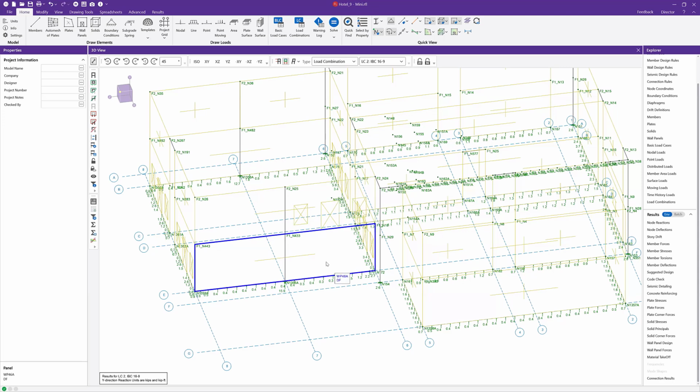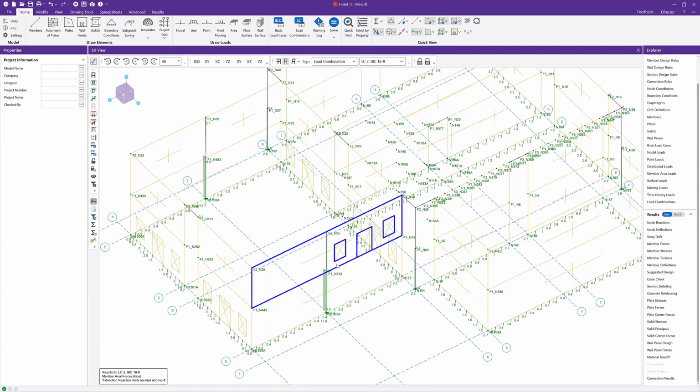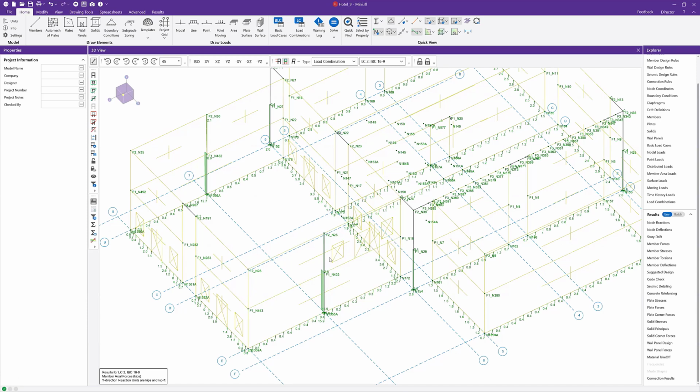So basically you're getting pure axial load taken by that particular column. We can also look at that. If we look at the axial load as it goes down the model here, we can see that axial load in a perfect distribution, as if the load is all exclusively applied to that column, as opposed to getting dragged a little bit in and out of that wall and column based on the interaction of the stiffness that you have at that particular location.